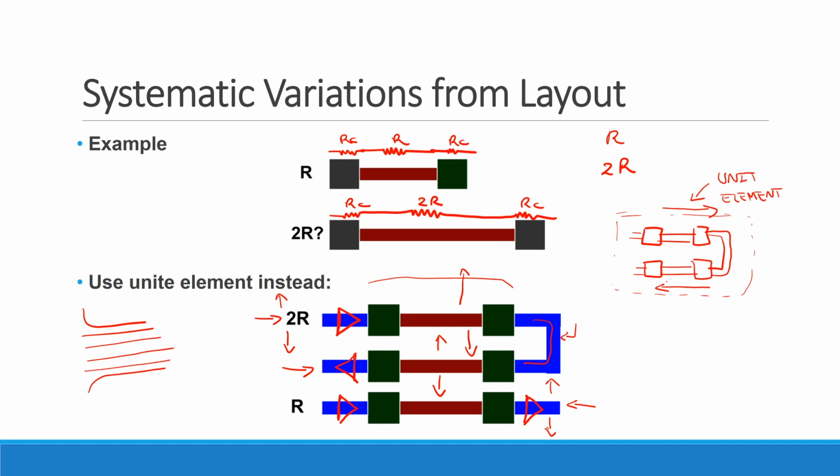Okay, so again, just to be clear, when you do real layouts in analog, you should do the same thing for MOSFETs as well. So anytime I build MOSFETs that I want to match, I make sure there's always two physical transistors, maybe with a shared drain, but I make sure there's two physical transistors there, just so that I don't make this stupid mistake. Okay?